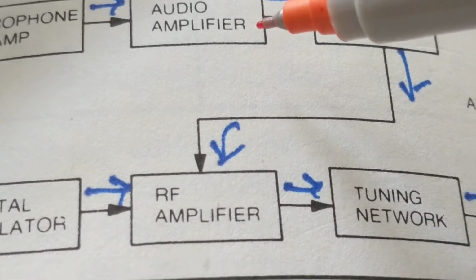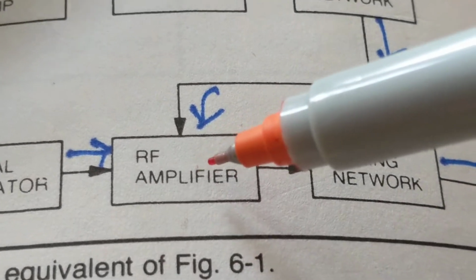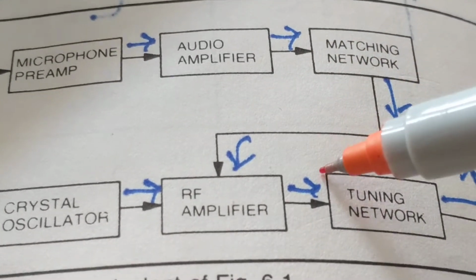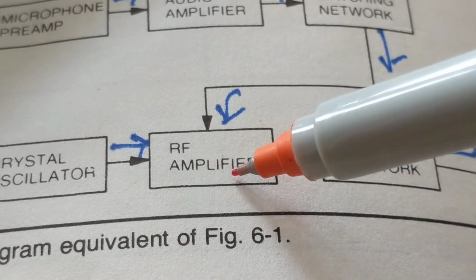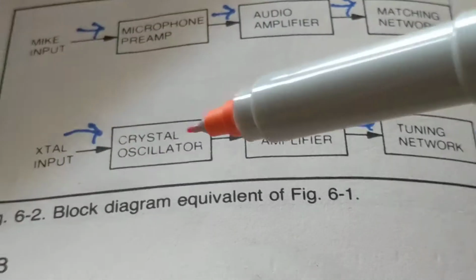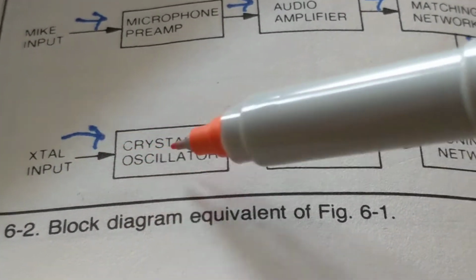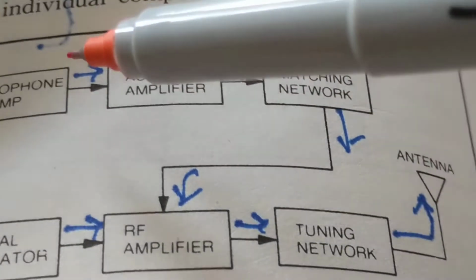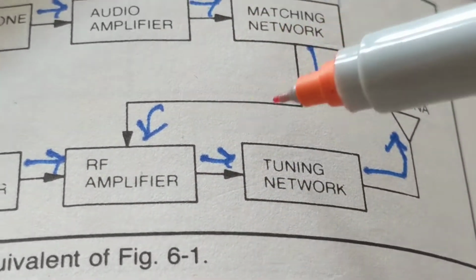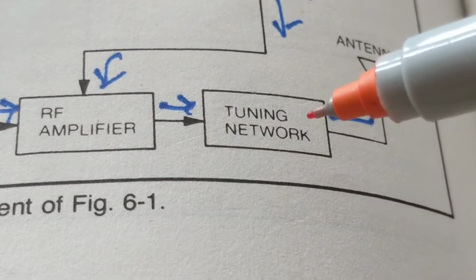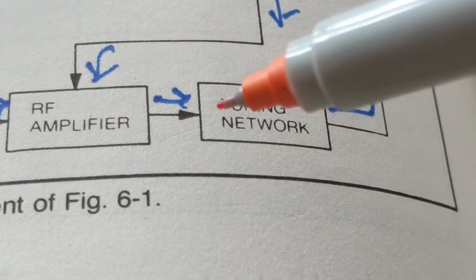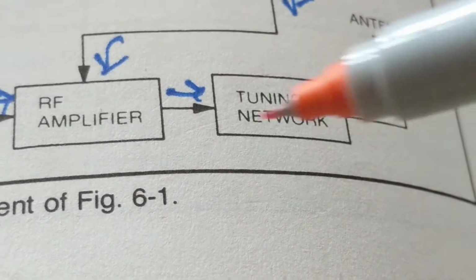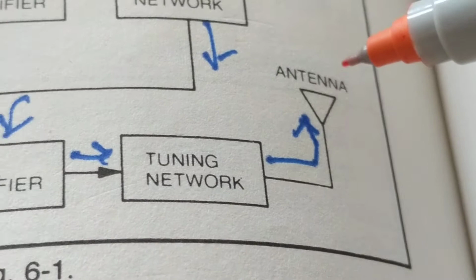1,000 hertz, 2,000 hertz, up to 10,000 hertz. The RF amplifier is in the megahertz. So this one over here is audio frequencies, and this is in the megahertz. Now, as you can see over here, there's something called a crystal input, which is a crystal that actually produces the high frequency. The intelligence, the audio, is carried on the carrier, the higher frequency, which is 28 megahertz. So you have 1,000 hertz being carried on, or superimposed on, 28 megahertz where it gets transmitted.